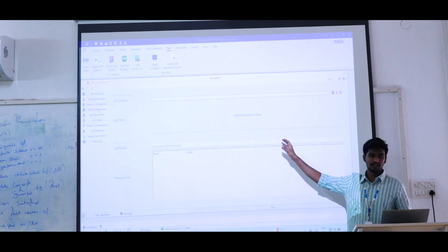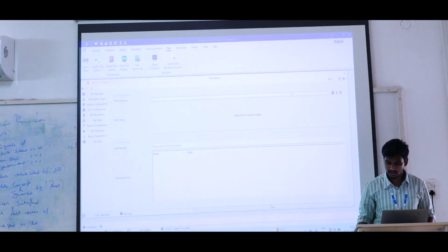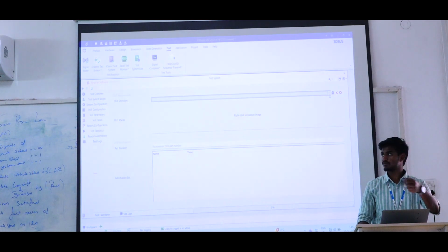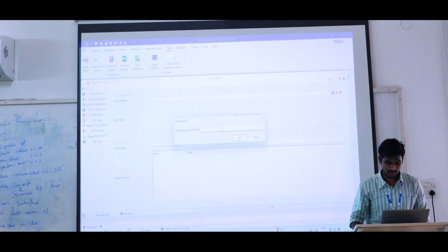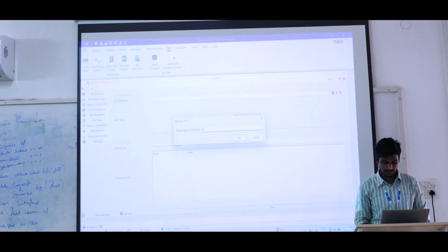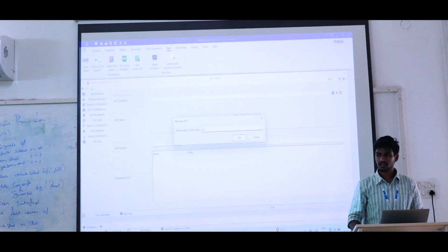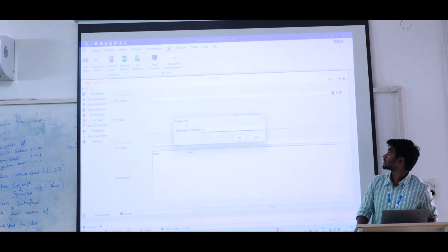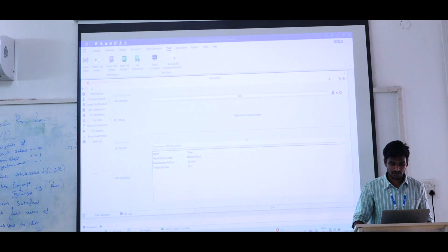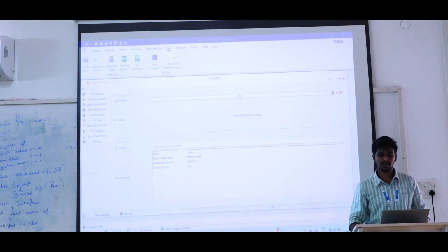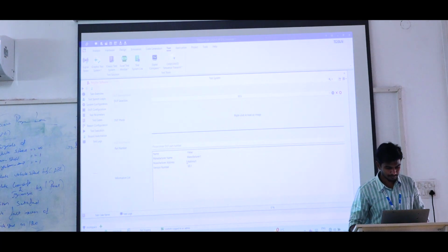So which one is available here? DUT, device under test. When we complete this, we are able to work here. So I have to create one additional one, temporarily typing it as ECU. In the DUT selection you have a plus symbol here. Just click it and it asks for a new DUT. Just type ECU and click OK. Now it is in the dropdown here. Select the ECU. Whatever ECU image you need, right click to upload it here.